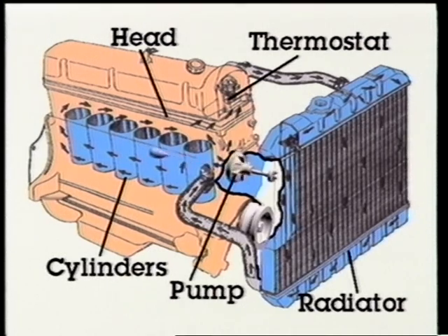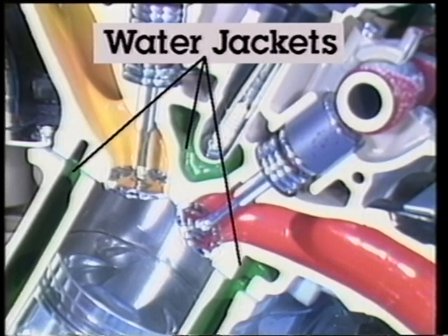It is normally operated by a belt running off the crankshaft pulley, but it can also be operated by a gear mechanism on the front end of the engine. The pump forces coolant through the radiator, up to the lower radiator hose, through the block, up through the cylinder head, past the thermostat, through the upper hose, and back into the radiator with most system designs. The flow of coolant through the engine collects excess heat. This heat is then carried by the coolant to the radiator for heat transfer into the surrounding air.